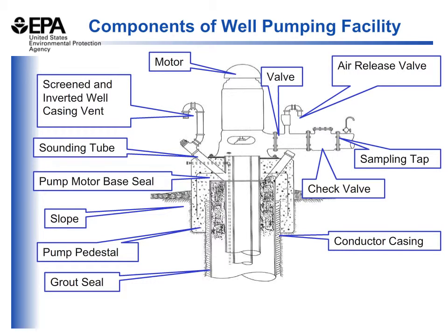In this situation, we have a pump where the impellers, or the collection system of the pump, are down deep in the well, and the motor that runs these impellers is placed at the ground surface on top of the well casing itself. This is fairly standard for larger water supplies. For smaller water systems, a fully submersible pump is used, where both the motor and the impellers are dropped down into the well and used to extract water from below ground.